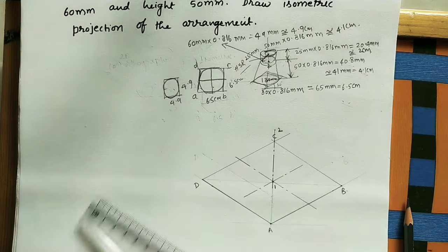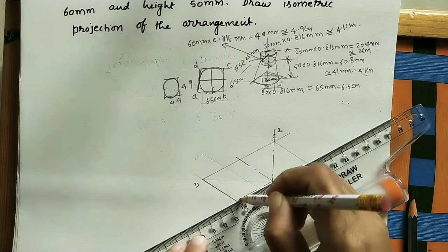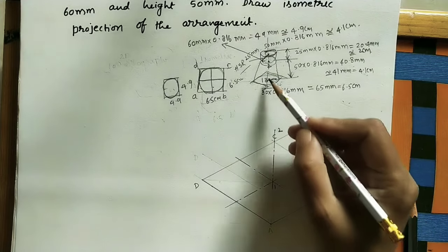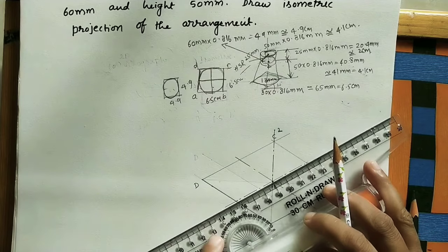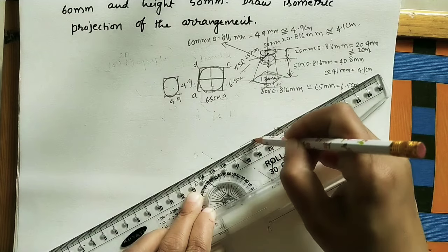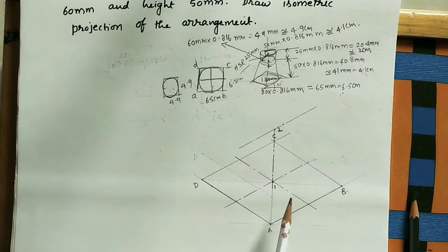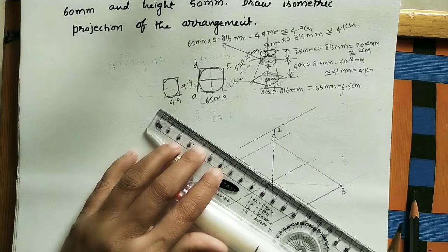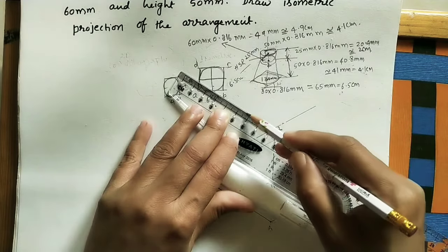Two big lines with a dot. Here also extend these lines. So at 2 center, do the axis lines. Take this as the reference line. Move the scale at 2, do the axis line. Like this. Okay, one axis line. Here also do another axis line parallel to this. Take the scale here, coincide with this. Move the scale at 2, do the axis line.